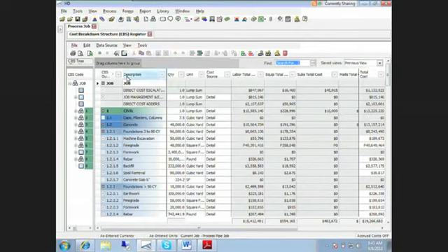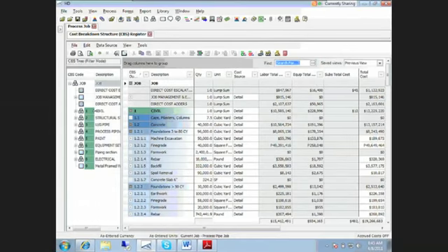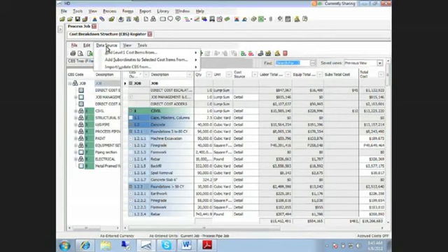All right, so this job's got various items in here. Let's take the scenario where we've done some takeoff in on-center. We want to see what those results are, and then determine what we want to bring into this estimate. What do we want to drive in this estimate from the on-center takeoff? So we get to it as a data source. Okay, so we go into data source, import update CBS, and then there's the new choice there for on-center.